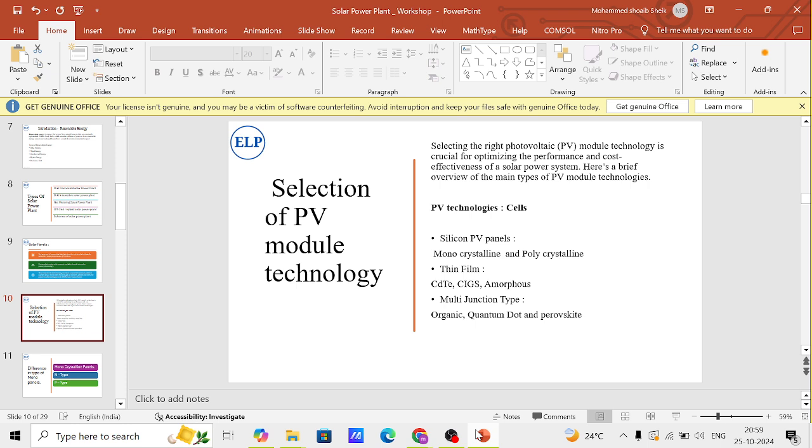If you have known about the Bangalore climate, for that condition, which is the best panel to be utilized? At that time, you can go with the polycrystalline. In the Bangalore region, we will not see that kind of huge temperature. It will not go beyond 32 degrees Celsius. At that time, your panel temperature will be not more than 40 or 41. But at that temperature, these panels will perform very well, and if you have a 100 watt panel, it can produce up to 110 as well because of the low temperature and high radiation.